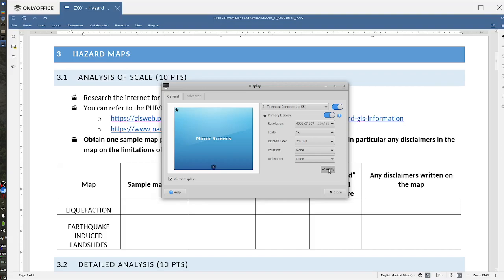If it's residential, I think they do something like mat foundations. In residential, your problem is not really the acceleration but the differential movement of your house.